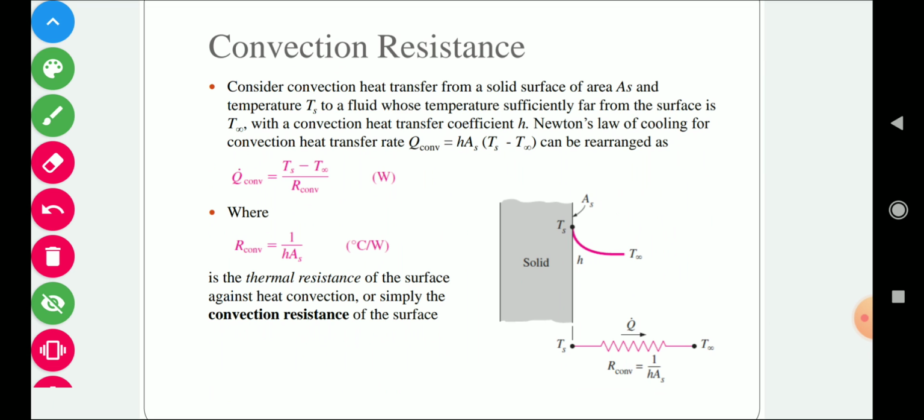Now in the previous example, we considered a wall through which heat is transferring. Extending this problem, once heat is transferred along the wall, it will further transfer to the environment through convection, because outside the wall we have some air, so heat has to dissipate to the environment through that air. And as I told you earlier, when there is actual movement of the fluid, the heat transfers through convection. So here we have air, so heat will transfer through movement of the air. So this will be a convective mode of heat transfer.